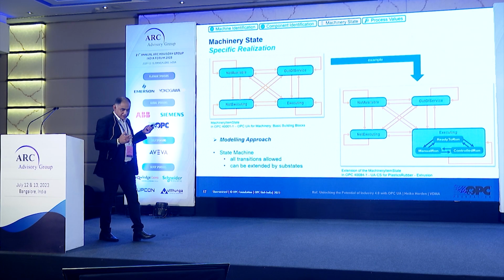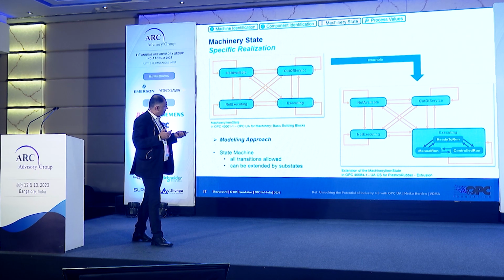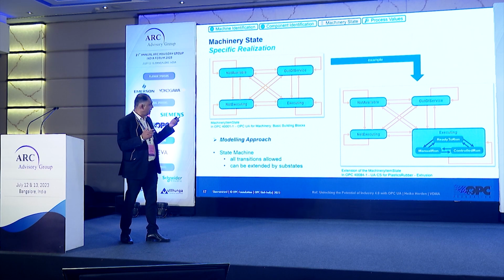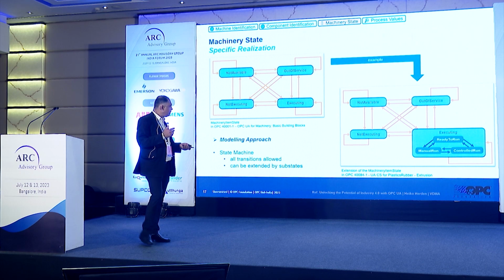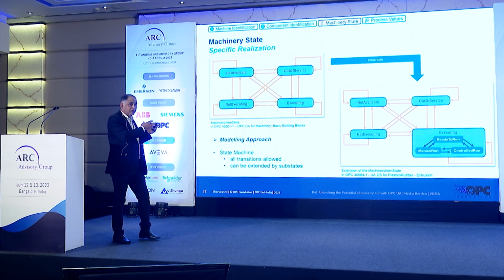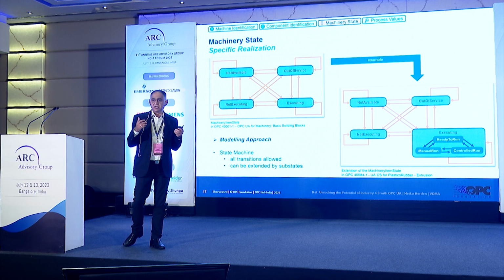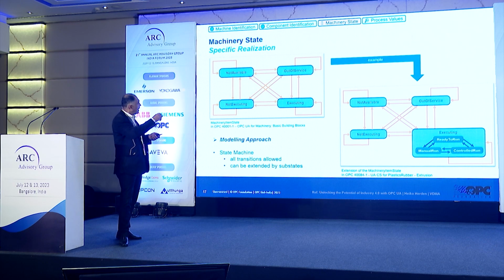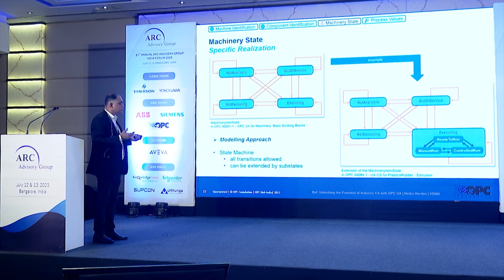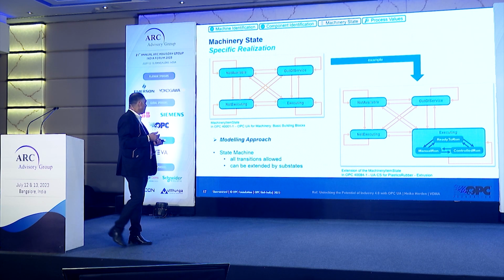And such a state model can be represented like this. And you can see here that you can also elaborate one of the states as, for example, executing states: ready to run, manual run, controlled run. So what it means is that once these 4 states are given, you can also derive your particular machinery states, which are very machine specific, under that particular structure. So it's a possibility to expand your machinery state depending on your machine specifications.